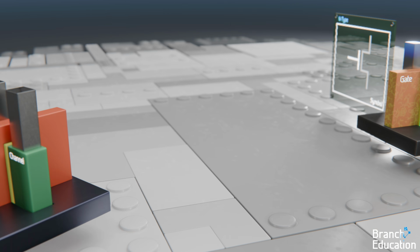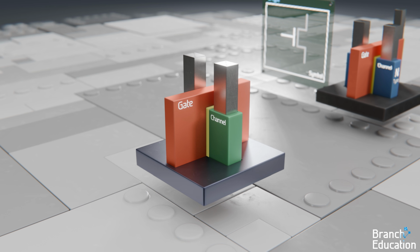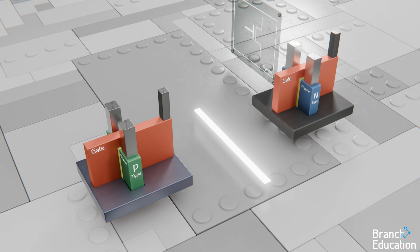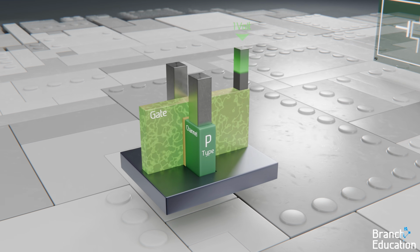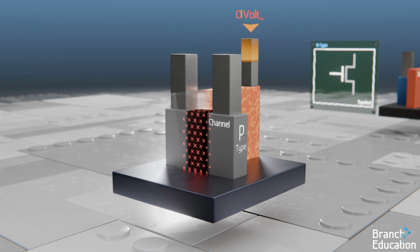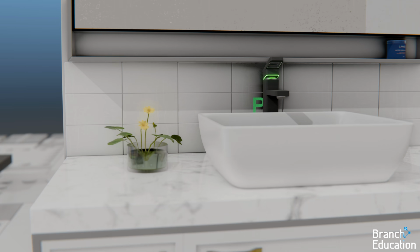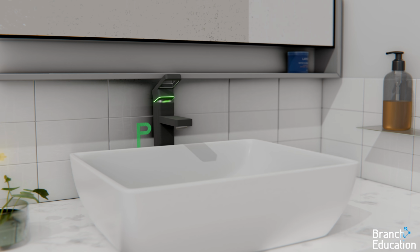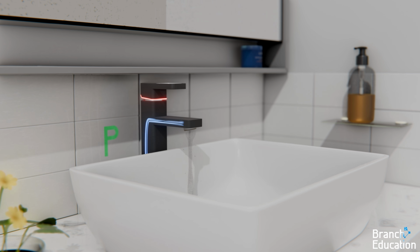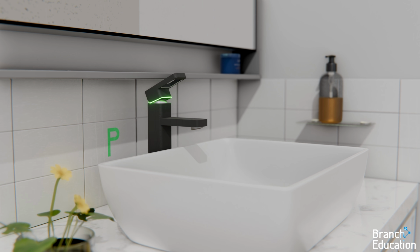Let's bring in a second transistor over here, which is the same FinFET shape, but functions a little differently and is called a P-type transistor. Specifically, it's designed to operate in the exact opposite fashion where, when 1 volt is applied to the gate, electricity cannot flow through the channel, and when 0 volts is applied to the gate, electricity can flow through. Using our water faucet analogy from before, this transistor is like a faulty water faucet where, when the handle is down, the water is on, and in order to turn the water off, you have to actively lift the handle.